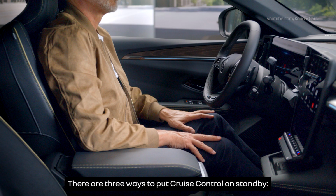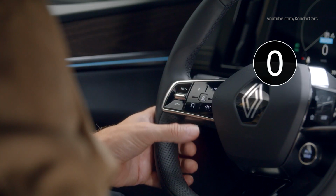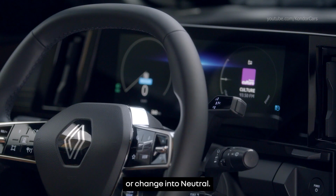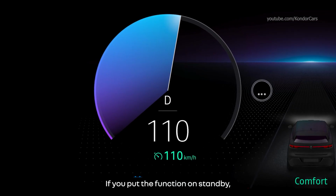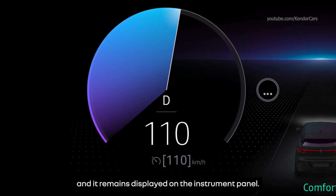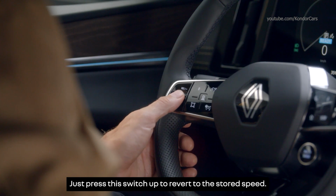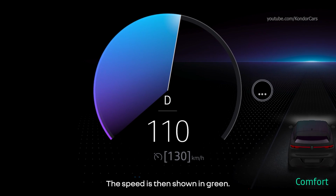There are 3 ways to put cruise control on standby. Press this button, press the brake pedal, or change into neutral. If you put the function on standby, your speed is saved and it remains displayed on the instrument panel. Just press this switch up to revert to the stored speed. The speed is then shown in green.